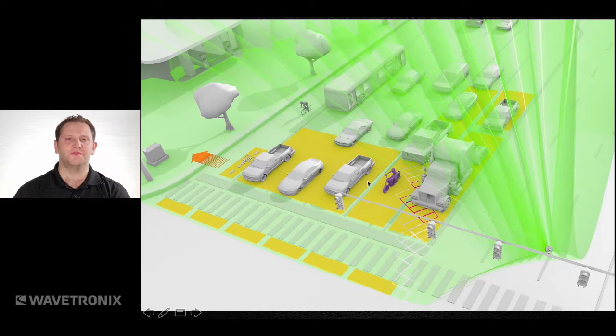Coming back to this slide here, I wanted to show this. So there's the bicyclist here. I wanted to show specifically the cells. These cells can be 2 feet tall, and the width gets bigger as it goes out. It starts really close, about 1 foot, and then it can get up to about 6 feet out here. So when we're detecting bicycles, the key is that a bicycle needs to be a certain distance away from a car, and it's typically about 2 cells.